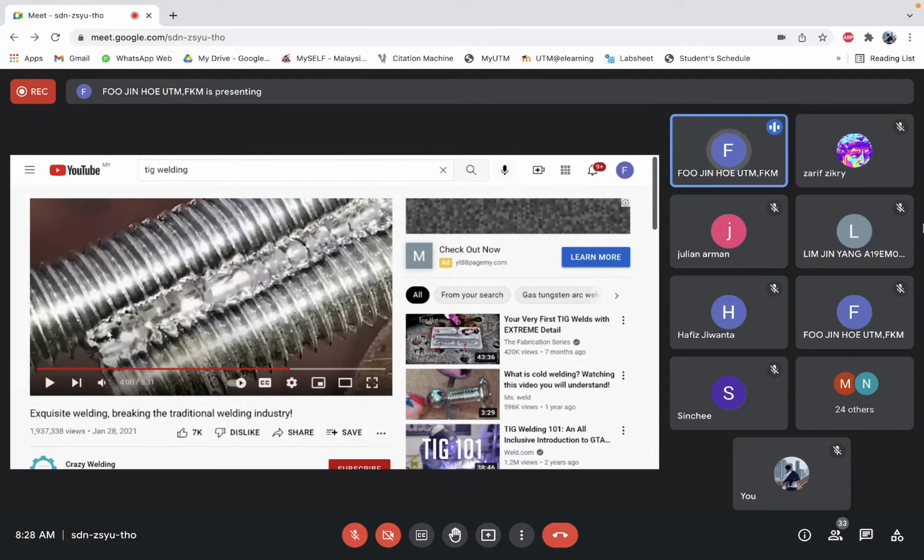So very clean welding is obtained, whereby you can see from the color that there are no outside contaminations. Normally, if there is any contamination, you will see some bluish, grayish, and purplish kinds of colors reflected on the surface of the metal. This is simply because this process is with the use of inert gas.